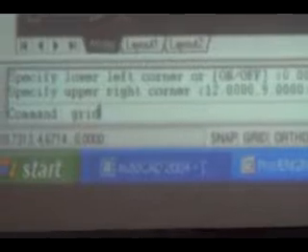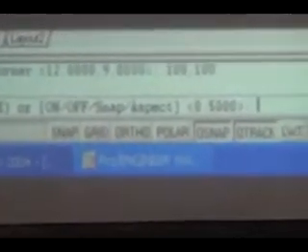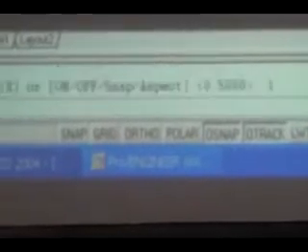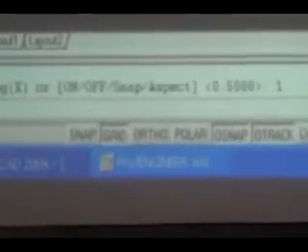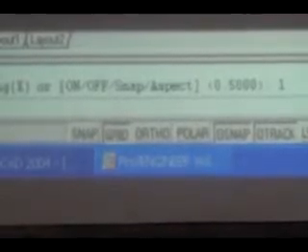if you want to show it, I can type grid. See, grid, it is asking aspect ratio, that is the grid spacing. So graph spacing, suppose 1 mm, 1 mm if you want. I have given the area 100, 100, x 100, y 100. So I'm giving 1 as a spacing. So can you see the grid? It's very light, but the grid locations are there.